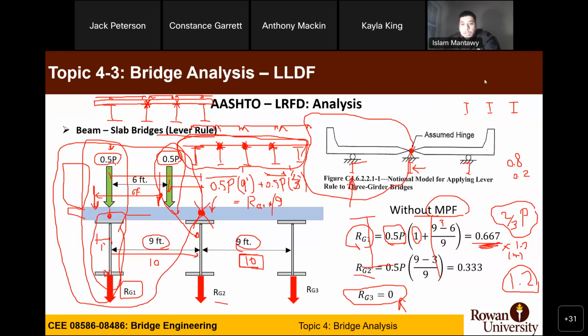Okay. So I got it written here. Maybe go back. I don't know how to erase it, but if your second girder is this one and the exterior girder is this one, correct? The distance here is 10 feet, correct? And you place your first axle, or actually wheel load, 1 foot off center to the left of the exterior girder, and this is half P.